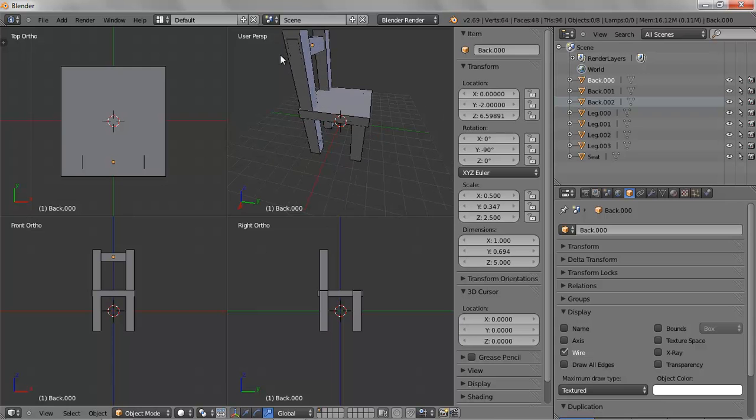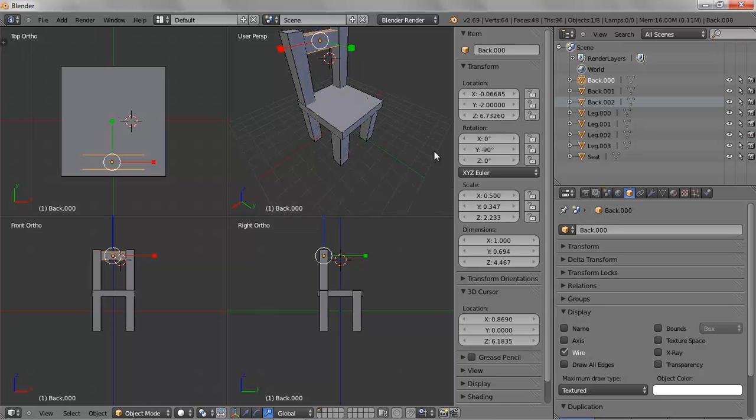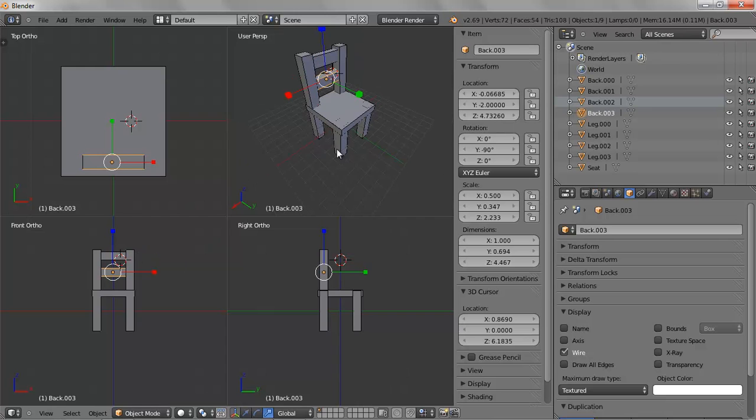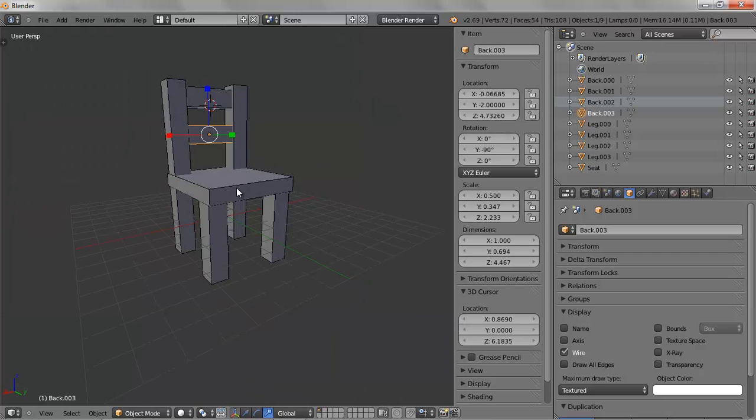Once you change the material, this is called Z-fighting. So you want to make sure that when you select the chair that it's either skinnier or it's wider. You don't want to do it kind of in between, so you don't want one exactly on the same surface as the other. And we Shift D one more time, grab, and add the back, and now we have a very basic chair. Now keep in mind that if you look at the reference images, which you'll be doing for homework, the chairs are actually much more elaborate and there's more pieces. This is just to get you started.